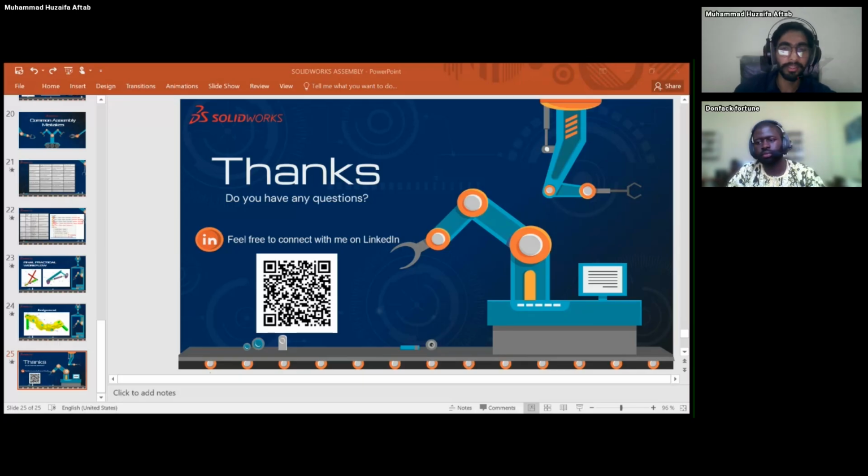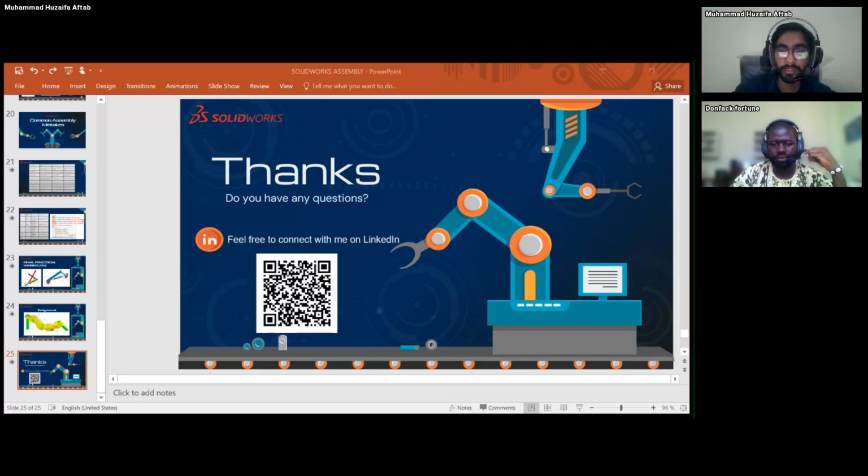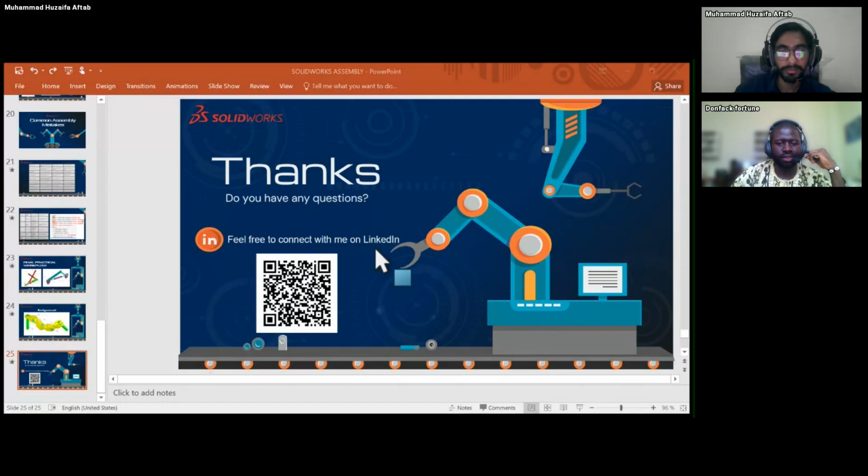Then we can easily make the circular spherical part inside this connecting rod. When I make this transparent, you can see that we firstly make this part like that, so we can easily mate these two parts.